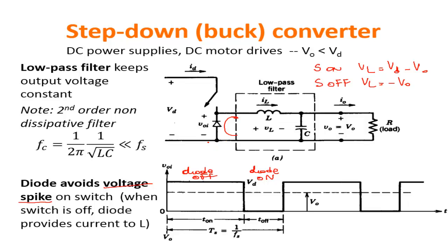So you see, the situation is now pretty simple. The main knob you have in order to adjust the output voltage is the duty cycle of the voltage controlling the switch. If you increase T on with respect to Ts, you increase V0. If you decrease T on, you decrease V0. And then the regulation would occur exactly by controlling the output voltage and, as a consequence, adjusting the duty cycle of the switch.